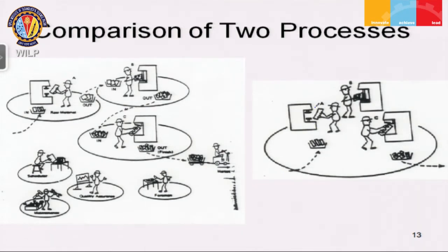Scheduling does not have to take place for each one of the three operations. You need to ensure that you have this particular part which is fed to the first operation, and from that point on this thing works in sequence, so that individual schedules do not have to be given to each one of the three operators. And to a great extent, when you have this kind of a configuration, you also tend to have the workers at least take care of part of their own maintenance of the equipment. May not be the major maintenance, but at least some of the simpler part of the maintenance.